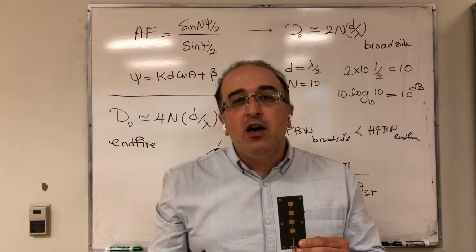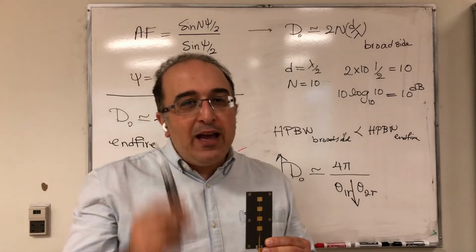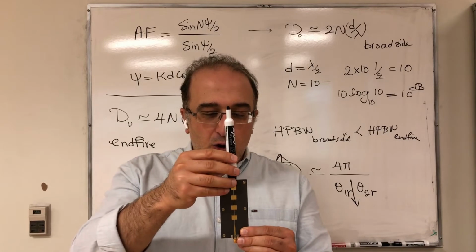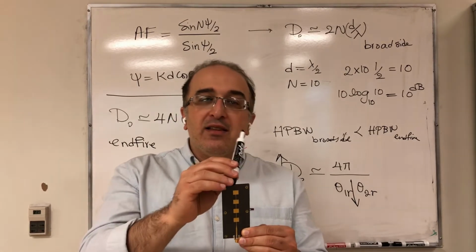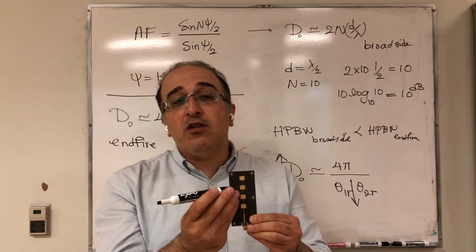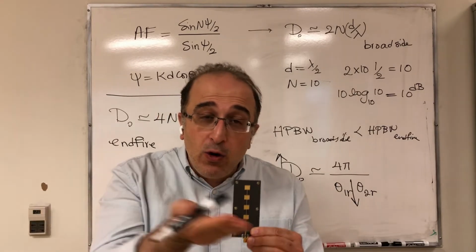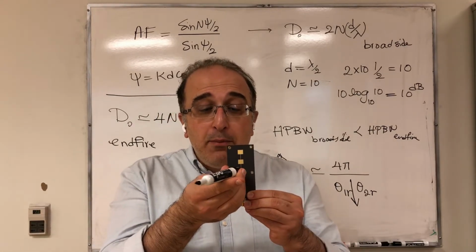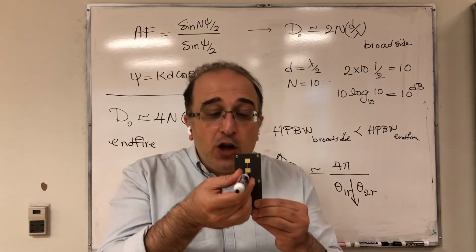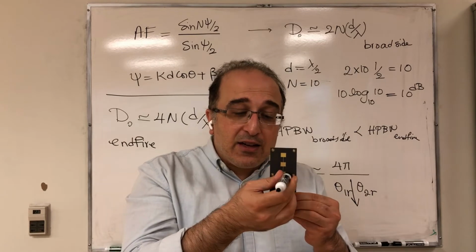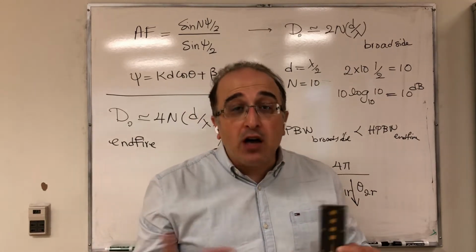But imagine now you have broadside, for example. Broadside means your main beam is at theta equal 90. So you go again, theta equal 90, but then every direction theta equal is going to be a theta equal 90. So essentially theta equal 90, as we learned in the course, is the whole xy plane. So essentially the main beam of the antenna is going around the antenna, is not only in this direction, is actually covering the whole xy plane when we say broadside antenna.